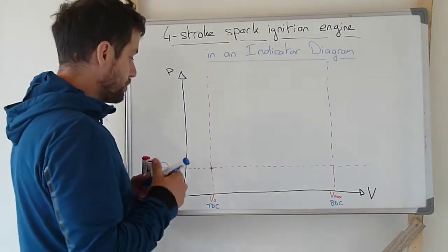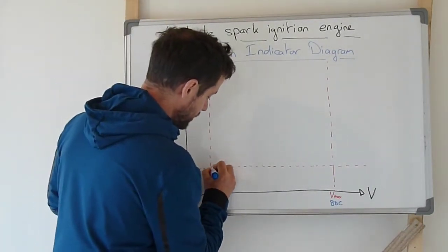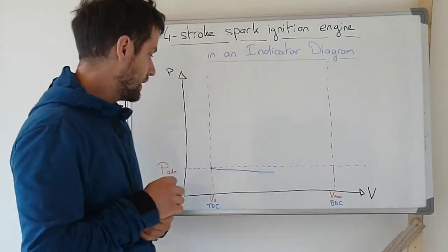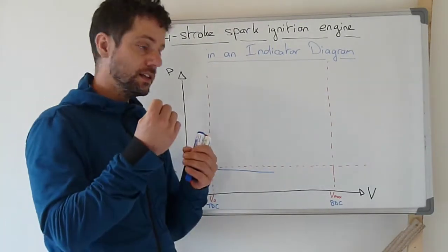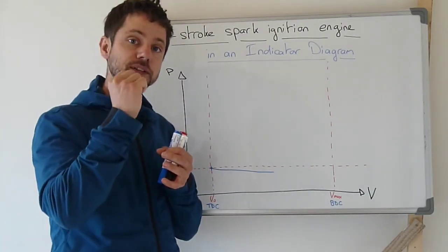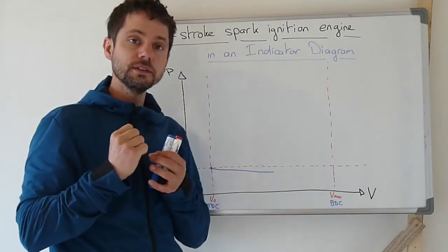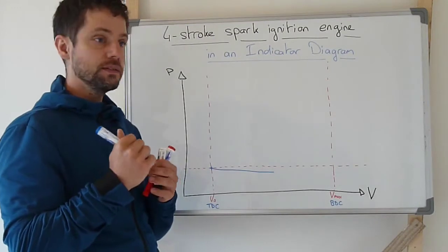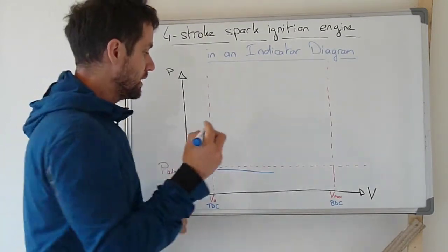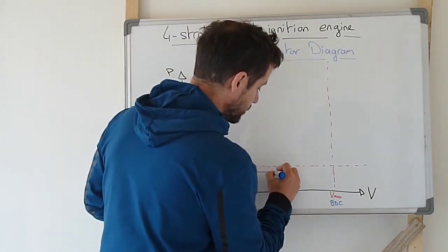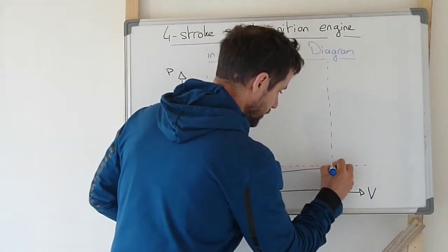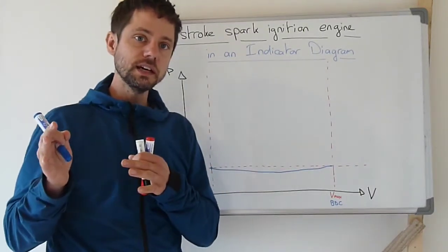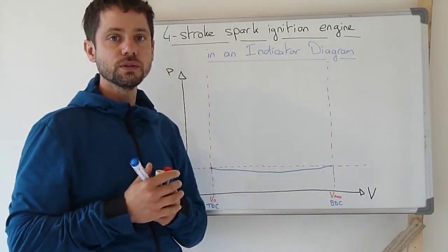So if we measure it, we can see that the pressure is slightly decreasing during this first phase, and at the end of the stroke, the piston will slow down because we have a sinusoidal movement. And so because the piston is slowing down, the flow is slowing down, and the pressures are equilibrating again. We get again the same pressure inside the cylinder and inside the admission line at the end of this stroke.